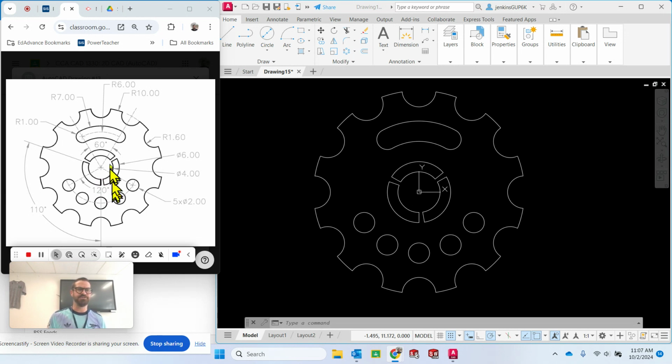And a polar array tool, just to reiterate really quickly, lets us take an element, for example like this little scooped out semicircle right here, and instead of having to do it again and again and place them all exactly where we want them to go, it allows us to create one and tell the CAD program, I want to repeat that element in a circle around a given center point. Maybe you want to do it 10 times, 12 times, 3 times. Maybe you want them to go all the way around the circle, or maybe just halfway around the circle. Or maybe you don't know how many you want, but you know you want there to be 1 inch along the arc in between each one of them.